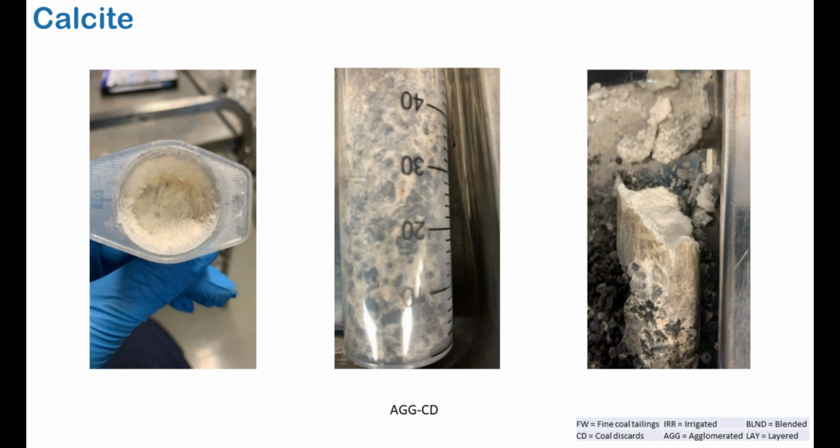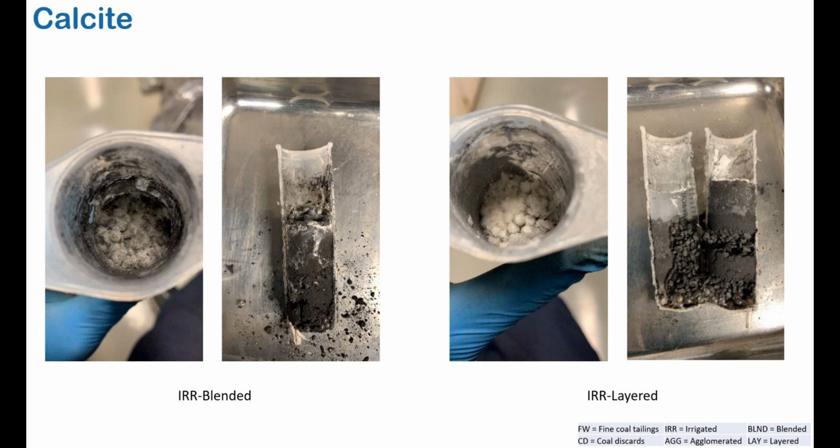Due to the large pore size present in the coal discard bioreactors, there was sufficient oxygen for bacteria to thrive, and it was likely that a small pocket of cementation solution was upheld, and this led to crystal seeding, which then grew to impede solution flow through the bioreactor. However, the crystal seeding in the coal discard reactors is unpredictable due to the packing limitations and the large pore sizes associated with this material. Calcite content alone does not translate to an improvement in structural stability.